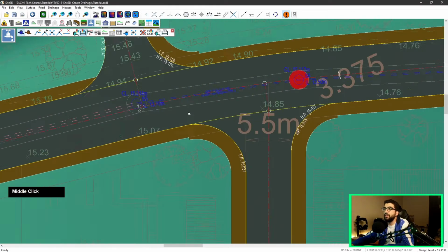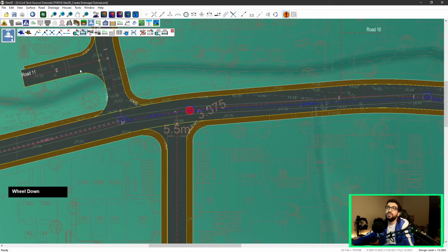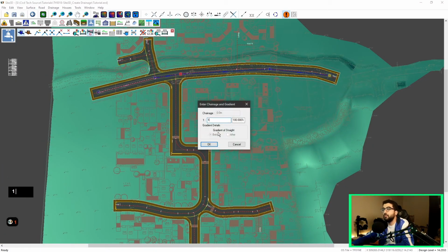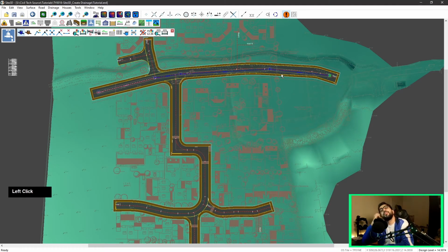Okay, so it fixed it by causing the problem there. So it's most advisable to just select one gradient, 150. I think this is good for preliminary design because you know the outfall, so you can work it from backwards. Let's say an average gradient, for example 150, because depending on how much area you've got, the pipe size would remain pretty much between the range of 150 to 300 if it's a medium area, but then it can become even bigger depending on your area,